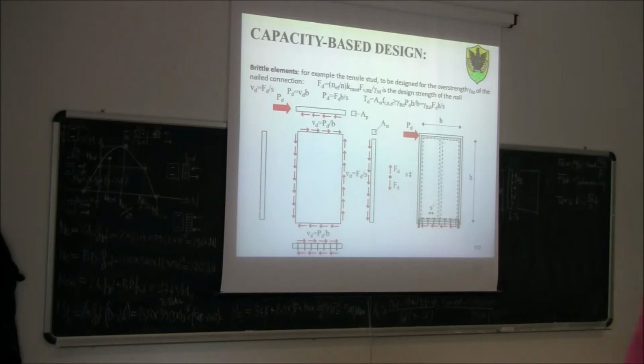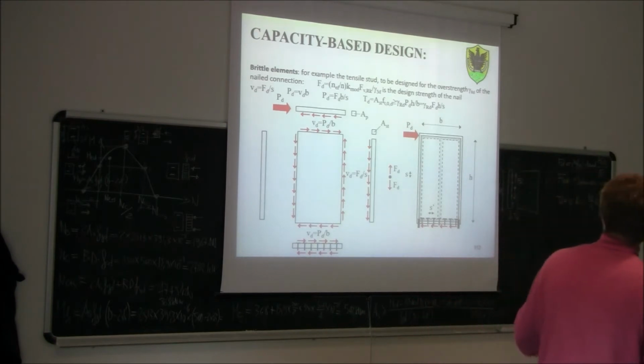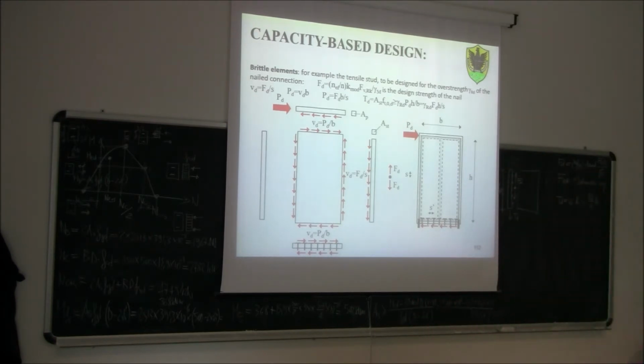So, to design this stud subjected to tension, since this stud has a brittle failure mode, because tension is a brittle failure mode, I cannot design this tensile member by basically the actual seismic force, but I need to design this tensile member for the overstrength of the nail connection.